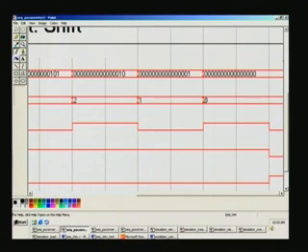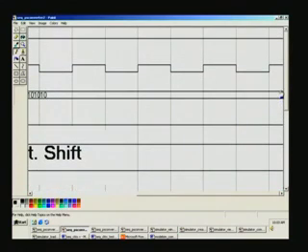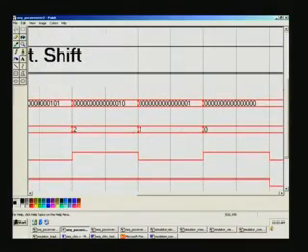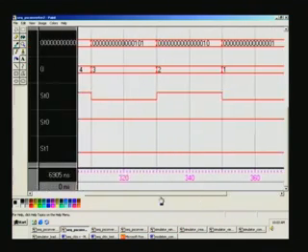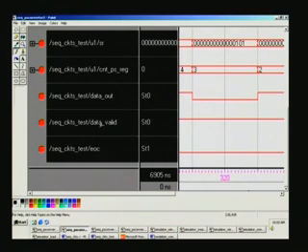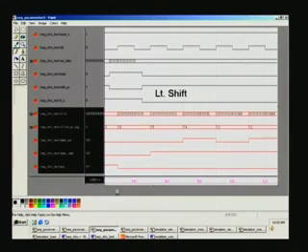And now you can see after this is over and all these transactions are taking place at the positive edge of the clock. You can just see here every time it happens, positive edge here, positive edge here. You can see this, and finally an end of conversion is asserted here. So, this is the last for the data, therefore data valid goes low. So, the last two are data out here and the corresponding data valid and end of conversion. So, this is for the right shift. Similarly, we can have the left shift here.